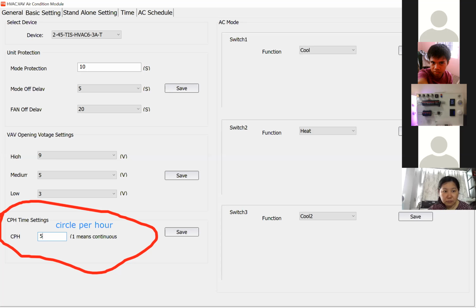For example, we have one heater. It takes too long to get cool. Therefore, we can put 2 here, because then it's on for 15 minutes and off for 15 minutes. Therefore, here you have saving energy. But if you have, for example, a model of heater that gets cold quickly when you turn it off, therefore here you can put 5.